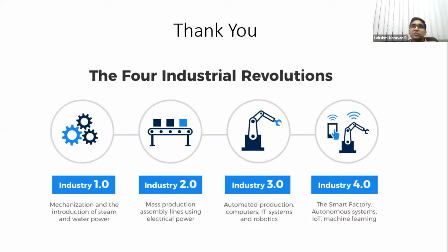Yeah, your knowledge is very good on this. This is a good question, but there's a problem with metallic glass again. If you heat the bed, the relaxation starts, and we don't like relaxation at all. Glass is bad at relaxation, and it's very sensitive to temperature. We want glass to be away from temperature. Unfortunately, in additive manufacturing, they have to raise it.